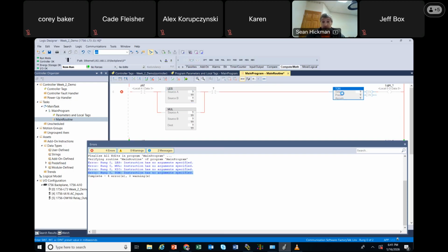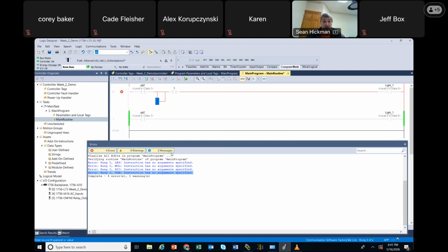And you can see if I just delete this, and this, and this, and then try to download it again. Let's see. Maybe I didn't. Oh, I didn't put anything on this tag right here. Right, so no argument on there. It takes me right there. So just click on the blue, and it will take you. Look, there's a warning here. Shorted branch detected. It's not an error. It's a warning. It will download with a warning, but it's just showing that there's a short there.